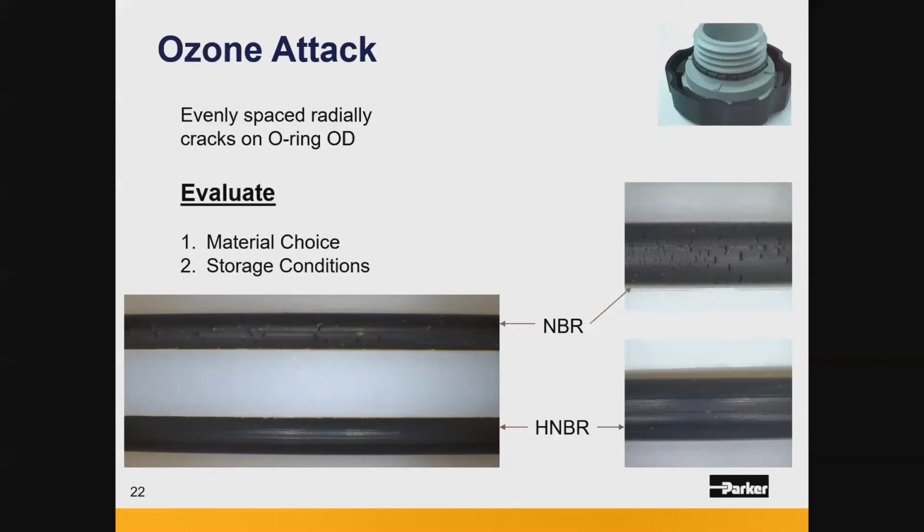This is even more likely to occur when the seal is stored in a stretched condition. So that should definitely be avoided. But whenever it comes to environmental sealing applications, we prefer to go with something like an EPDM or a silicone, or an HNBR if something higher temperature or more wear resistant is necessary. HNBR is hydrogenated nitrile, and it has basically undergone a synthesis process that removes the weak point in the polymer structure, allowing for that ozone attack.